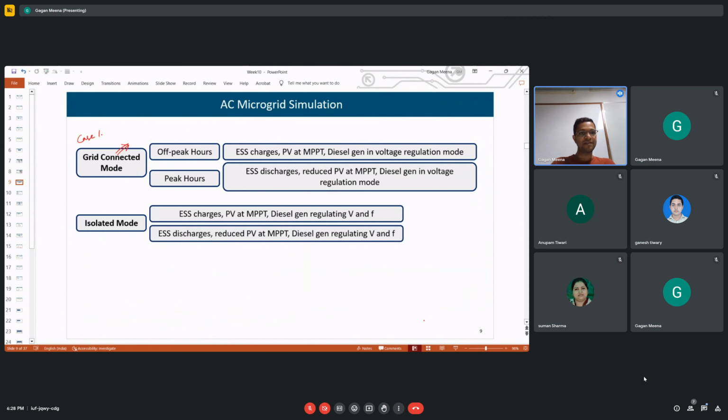So this is a low voltage DC microgrid, and the load requirement will also be lesser here, maybe 200 watts. And here the load requirement will be more because the voltage levels are higher. Two independent DC microgrids operating at different voltage levels can be interconnected. As we have seen, several advantages can be obtained by these interconnections.